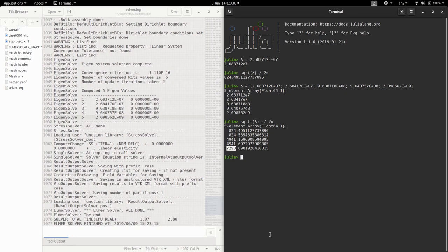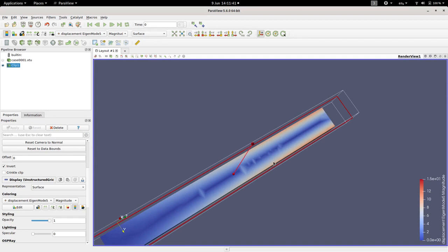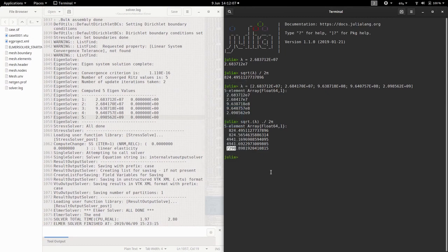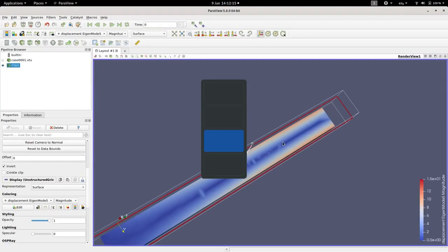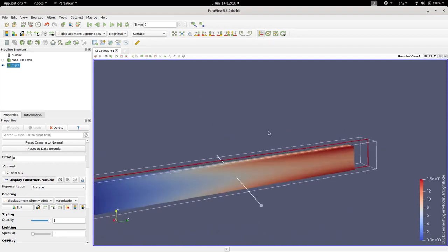It is a very high frequency, so probably what is going on over here is that our mesh size is too big to capture the displacement field with accuracy. So we should probably repeat our analysis with a smaller mesh value actually. I mean smaller mesh size, if you want to model the bar at such a high frequency with high accuracy.